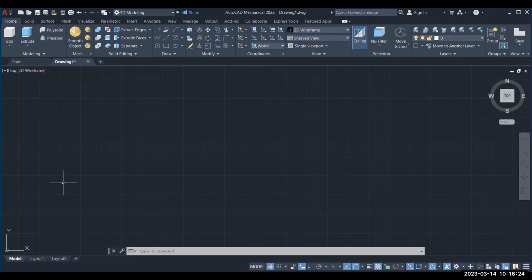All these different styles are offered by AutoCAD 3D. When you have constructed your 3D diagram, if you want to present it as a wireframe model, you can choose the wireframe visual style. If you want to present it as a realistic model, you choose realistic. And if you want to show it another way, like shades of gray, you can choose different types. This is one way of selection.